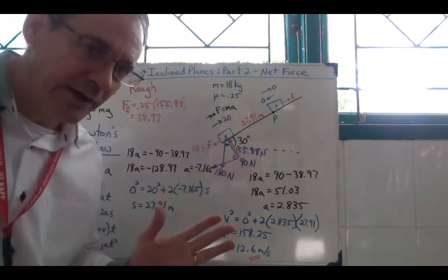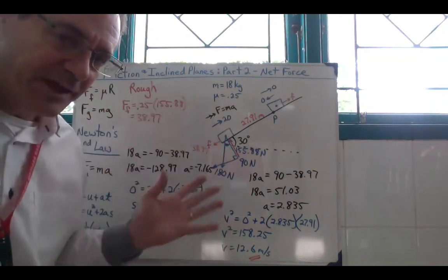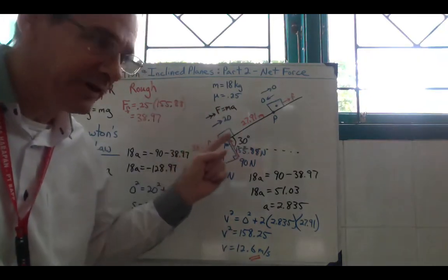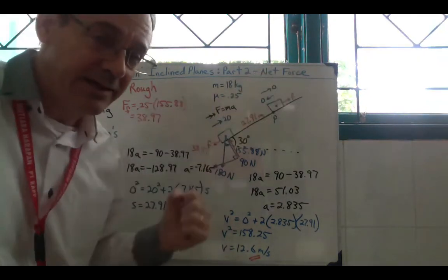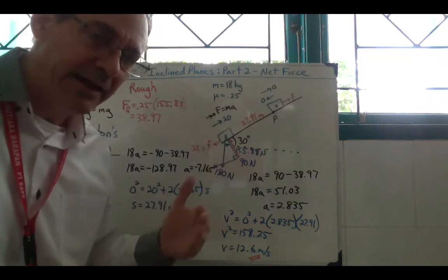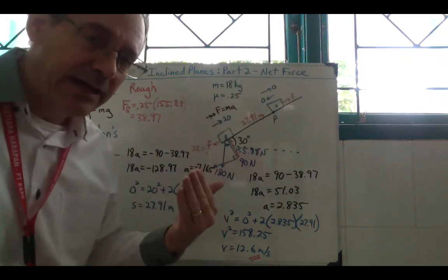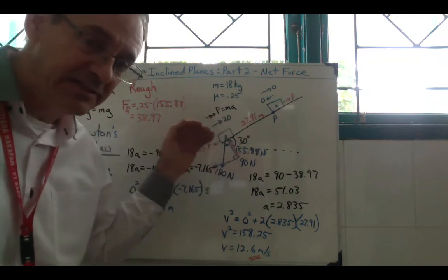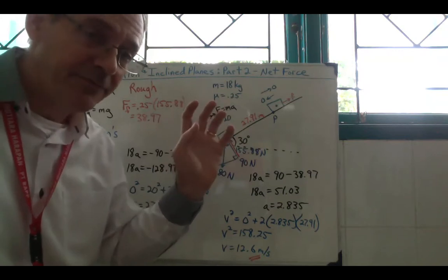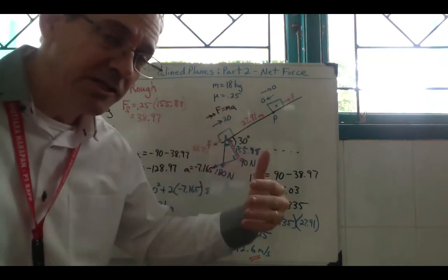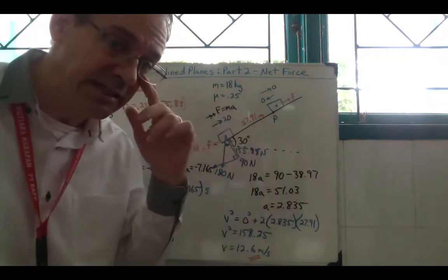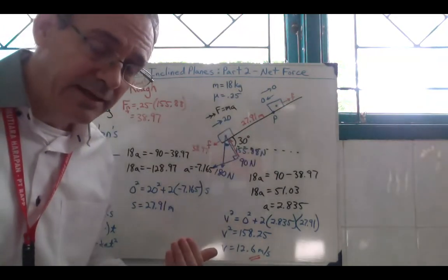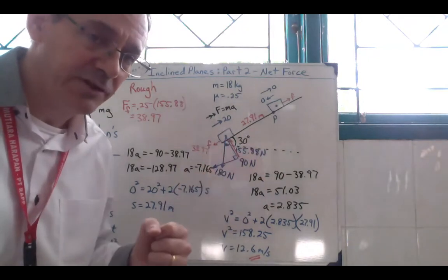Again, really quickly, those first things you need to ask yourself. One is the system in equilibrium, or does it have a net force acting on it? You tell that by whether it is either at rest or constant velocity means equilibrium, and if it's in motion or not constant velocity, basically not constant motion, then you have a resultant force acting on it.